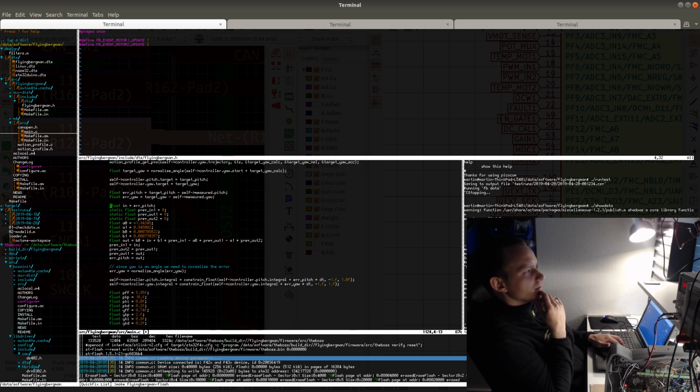And this is how a filter can be designed easily using MATLAB. Just calculate the values for the A and B coefficients for the filter. This can be done using the butter function, or any kind of filter function that outputs coefficients in MATLAB. I can then specify the cutoff frequency and design this discrete filter that runs at 1000 Hertz.